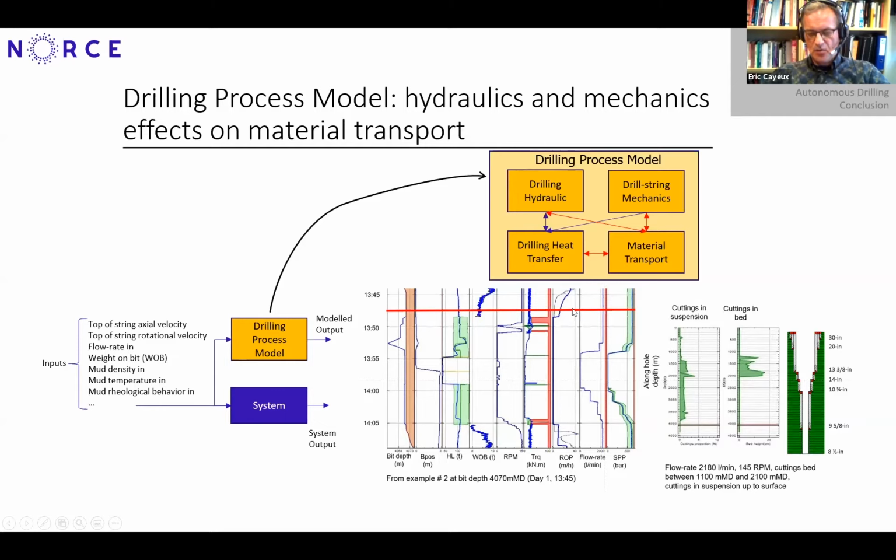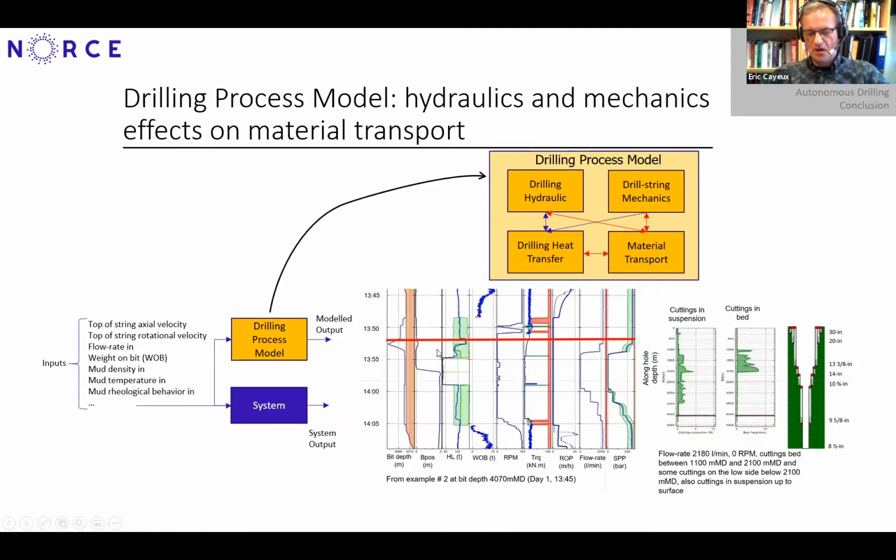Now, if we see here, when we are pumping and drilling and everything is okay, those cuttings are being transported to the surface. There is a cuttings bed. Just afterward, we stop the rotation because we do a friction test. And when the rotation is stopped, of course there are lifting forces to lift up the cuttings particles which are on the low side, and therefore more cuttings particles tend to settle on the low side. Nevertheless, most of the cuttings particles were estimated to be on the high side and therefore able to be transported during the friction test.